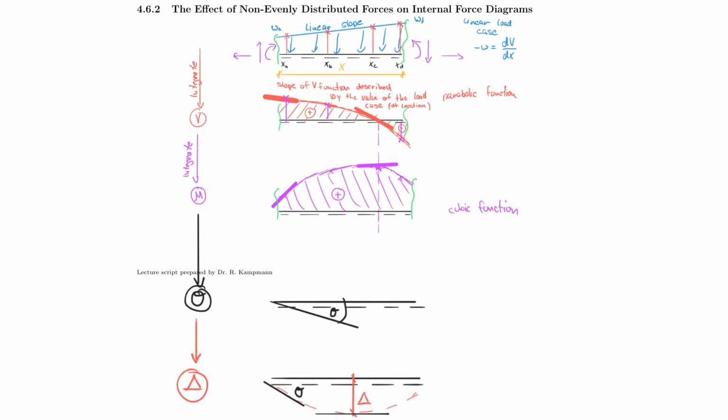And why is that important? Because engineers often build critical structures where the deflection needs to be limited. For example, if you have ever noticed that shopping malls have huge shopping windows, then you also have seen that there is a very long span length, and of course the longer the span is from left to right, the higher the deflection can be. So engineers need to ensure that this deflection does not get too large, so that the beam would not push on the glass beneath it. So the glass really needs some breathing room because it's so brittle, and engineers have to make sure that the deflection value stays within certain limits and keeps some room between the glass and the beam.